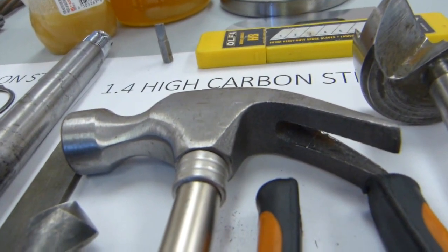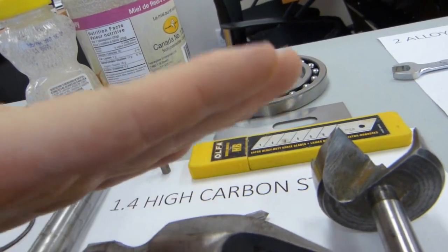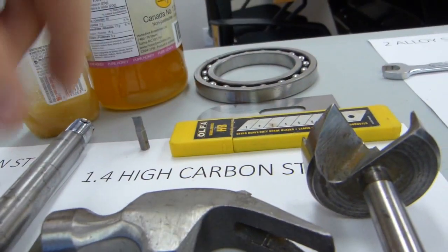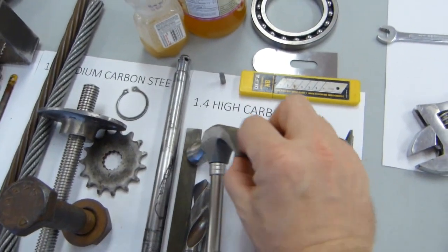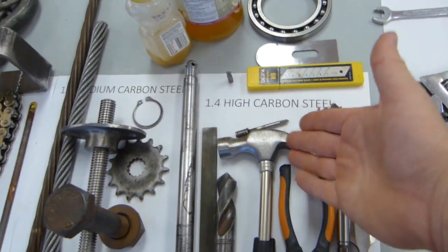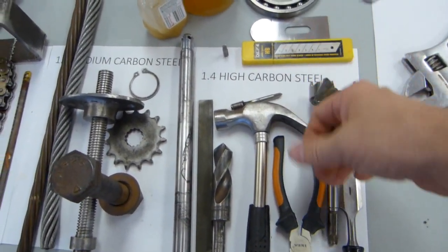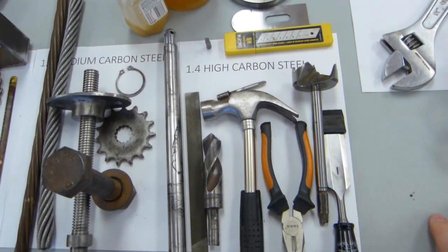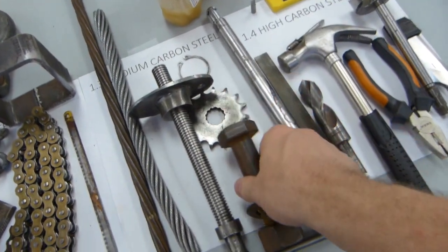Graphite is what you have in a pencil, and a pencil is meant to have the graphite layers flake off and shear off and leave a nice and even layer on the paper. So that's exactly what happens. If you try to weld back a claw on a broken hammer, it's gonna fail repeatedly along the original break line where graphite will be separating out. You can see it black, you can see it as soot, so there's going to be the graphite layer along which this will fail repeatedly if you try to weld back these kind of things. These ones are not so bad.